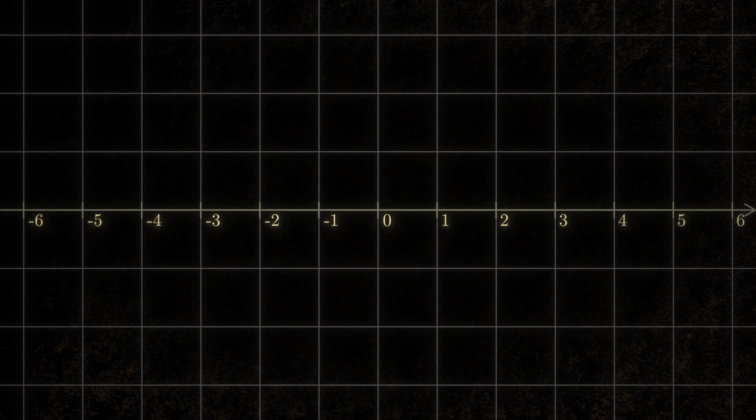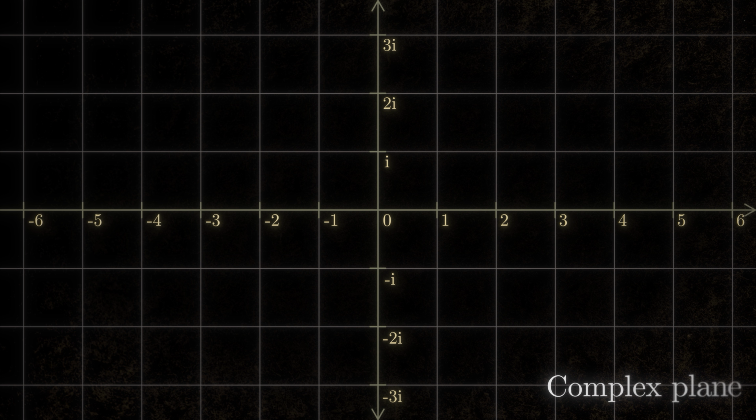Now, one common way to represent something with both a magnitude and a phase is to use complex numbers. They consist of two parts, a real part represented on the x-axis, and an imaginary part represented on the y-axis. This is the complex plane. Now, because electrical engineers used I to refer to current, we're going to refer to imaginary numbers with a J. And just to shake things up even more, most electrical engineering textbooks swap the order, so instead of saying something like 3J, we have J3.